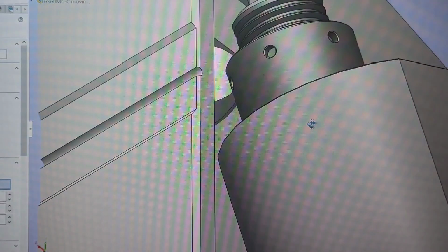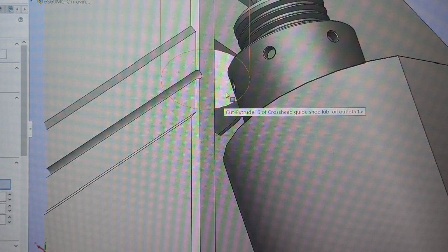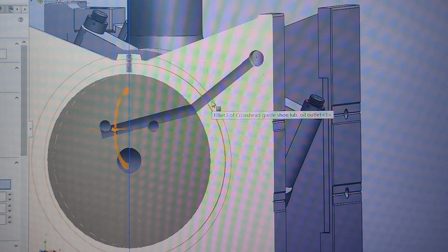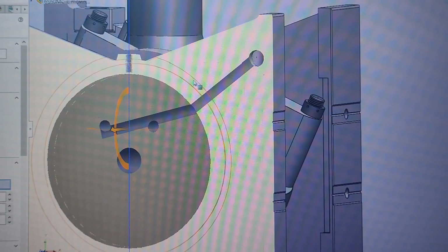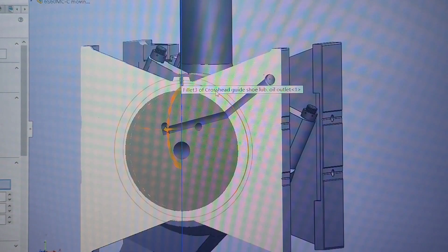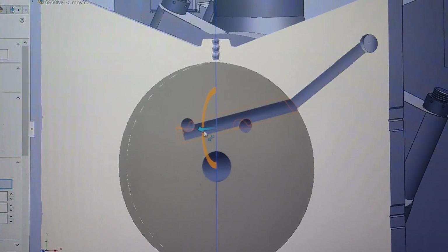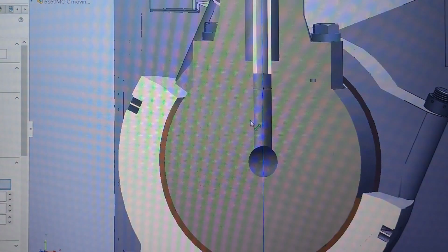The view is not that clear, but you can see they will reach here. They will flow down, alright? Because they are heated and might contain some contaminations because the oil is heated under the piston head, so they won't be used as a lubricant for the bearings. Now let's move back to here.